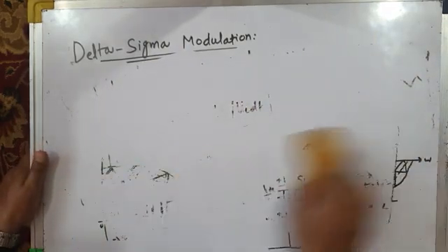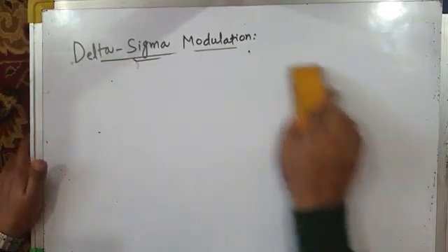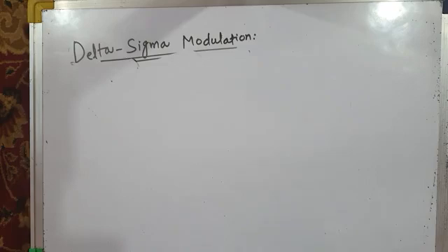Now, this is a current controlled PWM voltage source inverter. We have used hysteresis current control. And using hysteresis current control, we are basically controlling the load current.